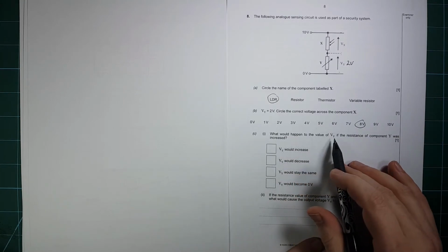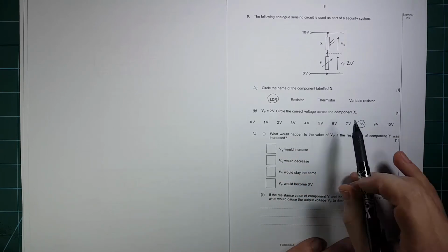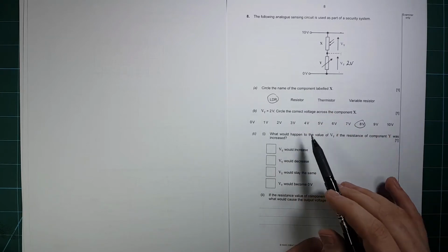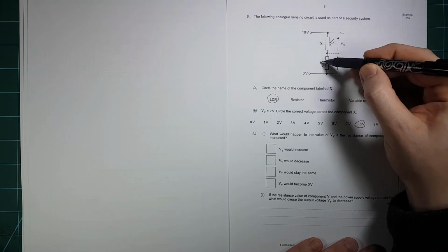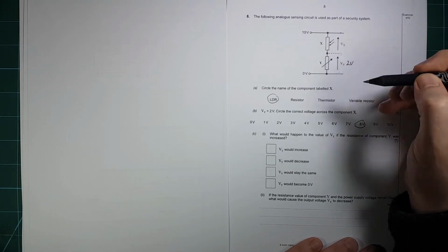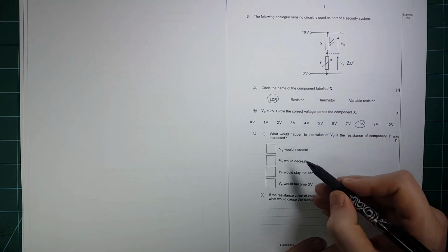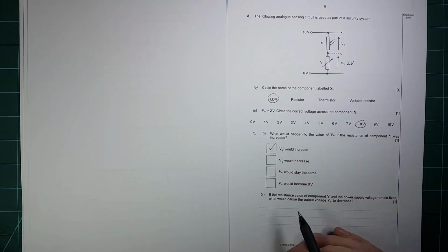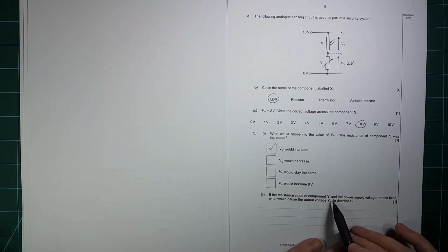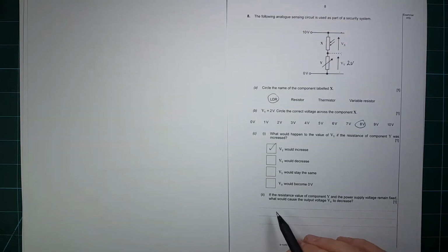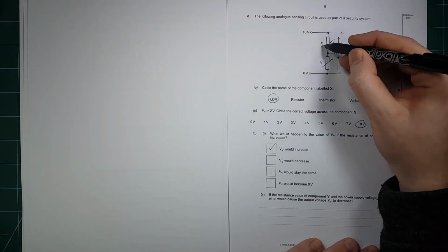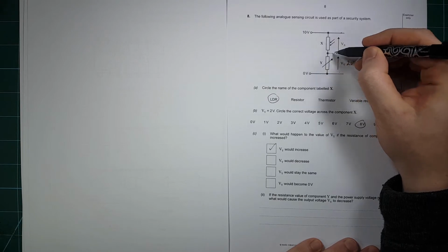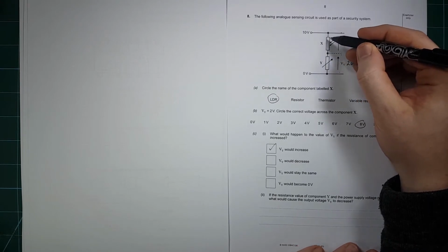What would happen to the value of Vy if the resistance of component Y was increased? Well, that would increase it. If it's got a bigger resistance, then its share of the potential would increase. So Vy would increase. If the resistance of component Y and the power supply voltage remain fixed, what would cause the output voltage Vy to decrease? Well, for Vy to decrease, this resistor has to get bigger, and so therefore you want